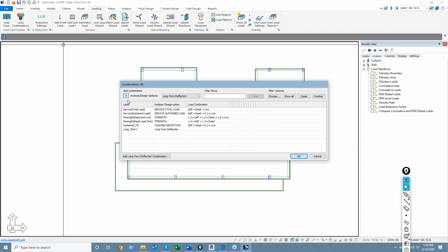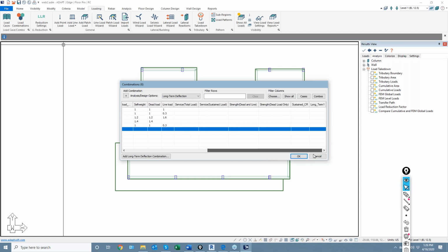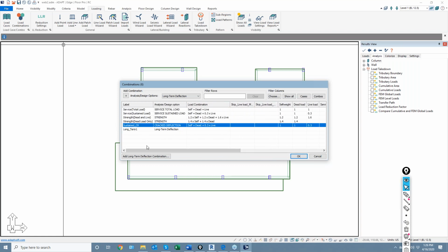This is, again, just a very simple example. So long-term, for this example, the creep factor we're going to just assume is 2, or maybe it's 1.5. It depends on what the user applies for the creep and shrinkage factor. We'll say it's 2, and we know that the long-term deflection is going to equal the creep plus the instantaneous deflection, let's say due to sustained loads.